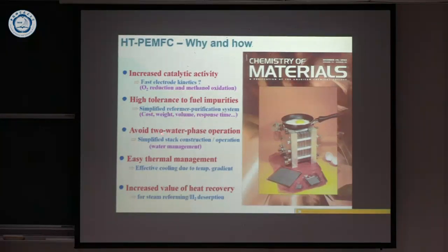You don't have two-phase water, liquid water and gaseous water, which makes the construction of the stack simpler. Thermal management is easier because you can couple the heat from a higher temperature level, and it even gives you the possibility to use steam reforming. So this is a summary of potential advantages.